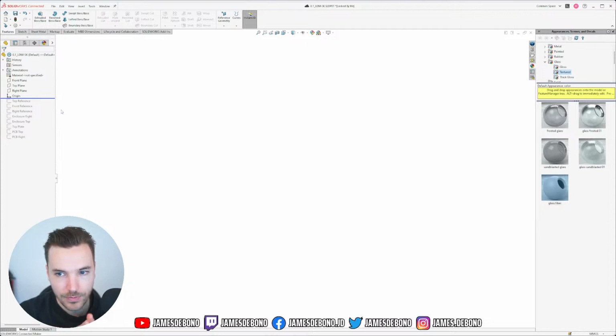So if I have a display and I bring in the sketch in here, then all of my cutouts for the display and everything will be based off the skeleton from that display. And if I realize later, like, oh, I actually messed up the dimensions of that display when I 3D modeled it, I can go into that 3D model, fix it, and then it should update everything here.